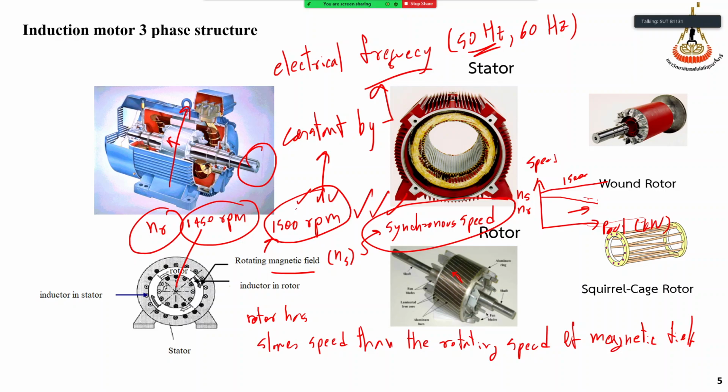So if we see a motor operating at a very low speed compared to its rated condition, it means the motor may be under overload. This is very dangerous and may burn the motor, with high current and heat that will not dissipate to the ambient around the motor because it is not rotating.